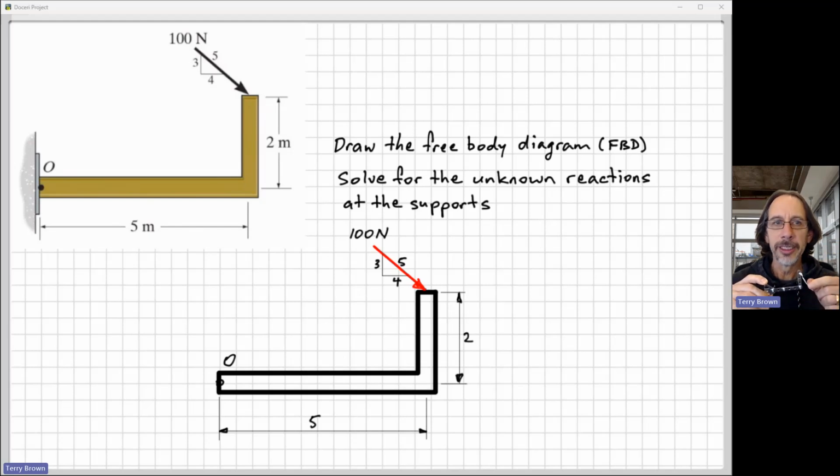In thinking about our supports, if you look at the little video of me just off to the side of the solution, you can see what I'm showing, hopefully. When we draw our reactions at supports, we think about the motion that's either constrained or is free. So in this case, it's completely built in. If I tighten this nut up really tight, so there's enough friction to stop it rotating, or if I put in two nuts here, then that can't rotate anymore. At the moment it's free to rotate, but if I draw my free body diagram to match this, it's not free to rotate, so I need to put in a moment reaction here.